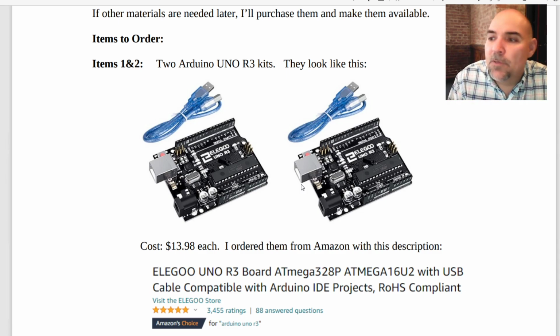And let me explain quickly what they are. This is what's called a microcontroller. It's a whole computer system on a chip. It's actually not a super powerful, multi-core processor like would be in a cell phone or a Raspberry Pi or something like that, but it's a microcontroller that's still pretty powerful. It's a 16 megahertz processor that's a RISC architecture, so this can do 16 million instructions per second, and it's designed for embedded systems. This little chip up here is the USB to UART converter, so we can talk to that chip and program it.